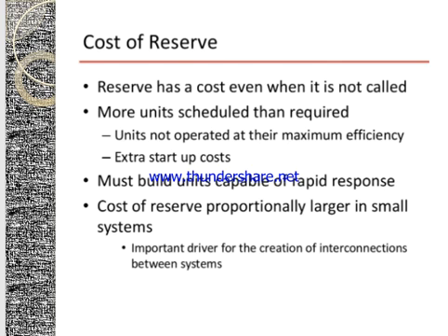All these reserves will incur a cost. Even when the reserve is not called, more units are scheduled than required, which means those units not operated at maximum efficiency will lead to an extra startup cost. So it must build a certain unit which is capable of rapid response. The cost of reserve should be proportionally larger in smaller systems. This cost of reserve is an important driver for the creation of interconnections between systems.